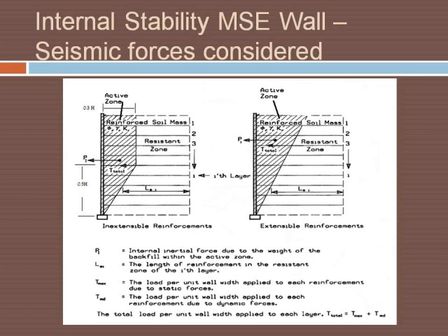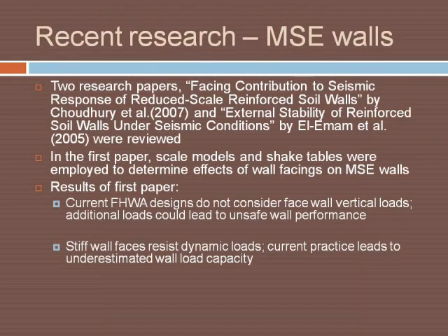internal stability forces that we talked about. You can see the active zones for extensible reinforcements and inextensible reinforcements are slightly different, and the other forces we talked about are shown on the figure. We looked at two research papers. One had to do with facing contribution to seismic response of reduced scale reinforced earth walls, and the other one was external stability of reinforced soil walls under seismic conditions.